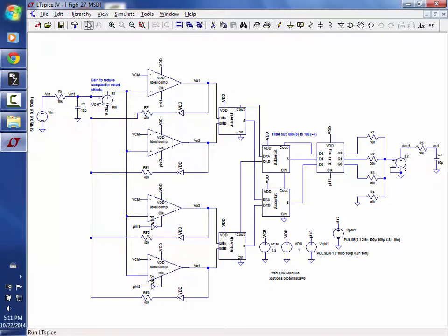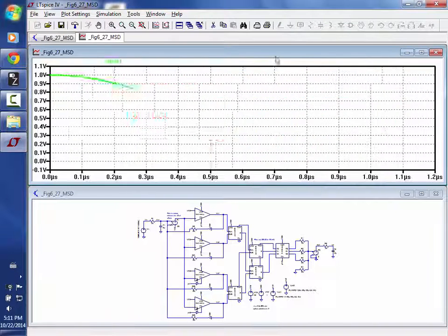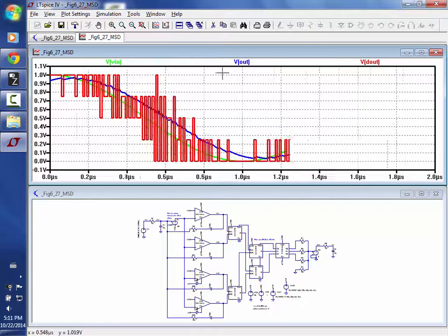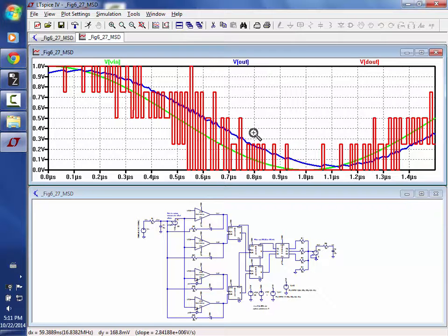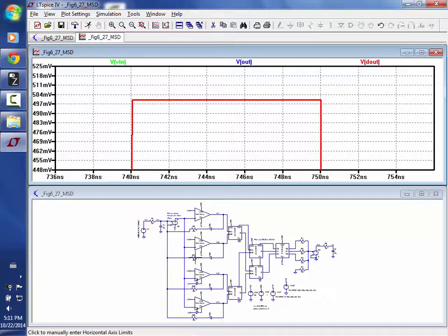So I go look now and run the sim. And now my pulse widths, I'll zoom in here for a second, that's my digitized signal, are all going to be 10 nanoseconds. Let's zoom in even more, from 40 to 50 nanoseconds. They're all changing. So now I'm essentially decimating and slowing things down.